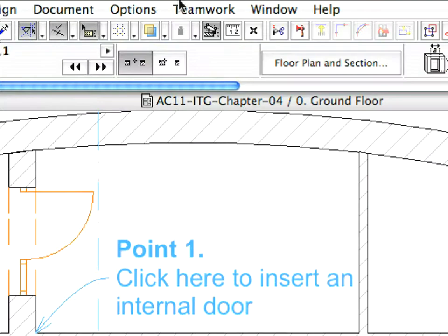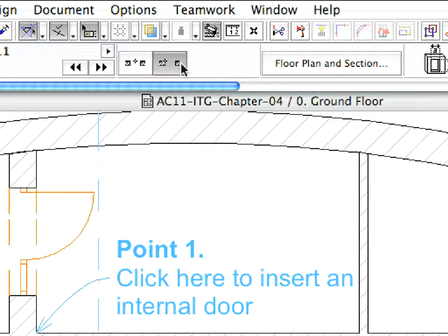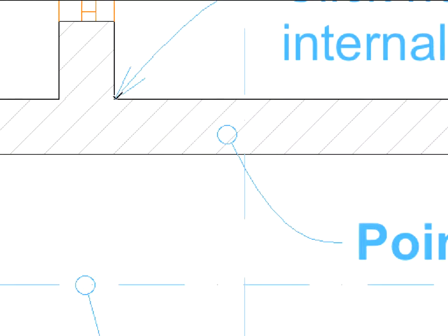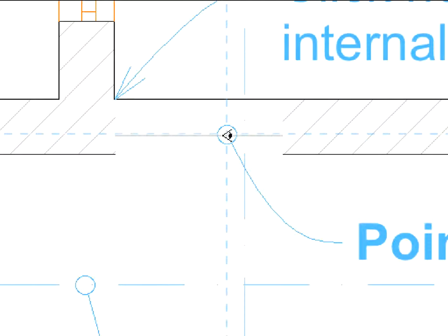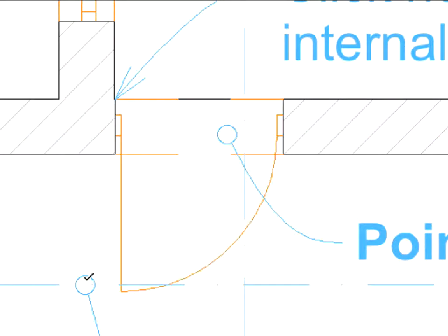For Geometry method, choose the Side option. Click to place the door on the internal corner point of the wall junction. Click to the right of the door in the wall to define the door position with the double I cursor. Finally, click below and to the left of the new door's center with the I-shaped cursor to define its opening direction. Let's add some more doors to the project, starting with the door for the bathroom area.